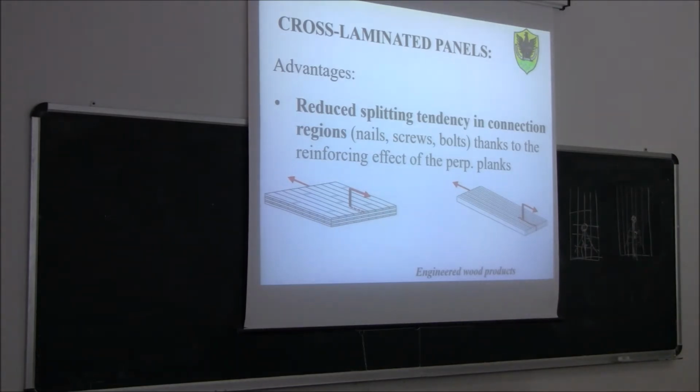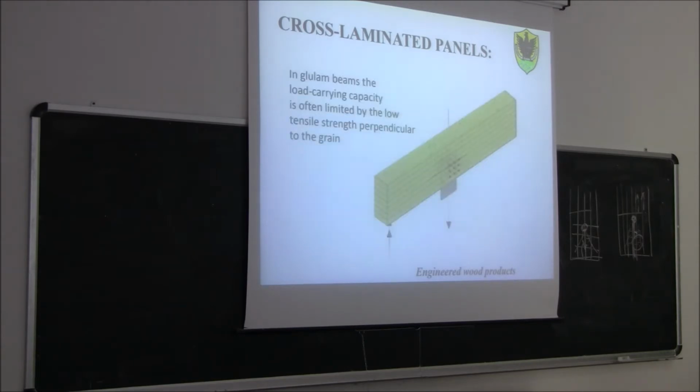Usually we know a problem like this in a steel region, if you do a steel structure, we never check the steel for secondary stresses. Why? Because steel is homogeneous, isotropic. So those stresses here are always much lower compared to the stresses in this direction, because those ones are secondary stresses. We learned that the strength in this direction is almost zero, it's 1 megapascal, while in this direction you get 20, 30, 40 megapascal. Okay? Good, so this is very important.